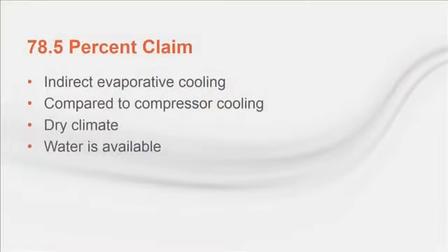And finally, is the comparison valid for your specific project in your location? As we covered in the ENL last year, using something like IPLV for chiller comparison is too simple, since it's the same in every climate and building, and not even close to accurate. So use the right tool for the job.